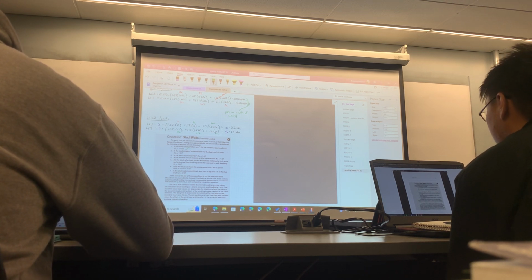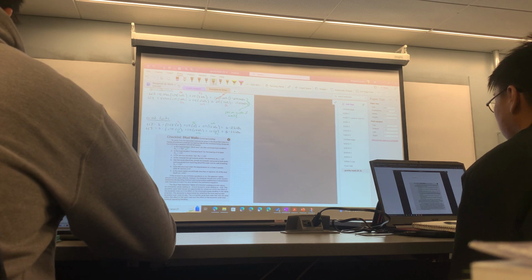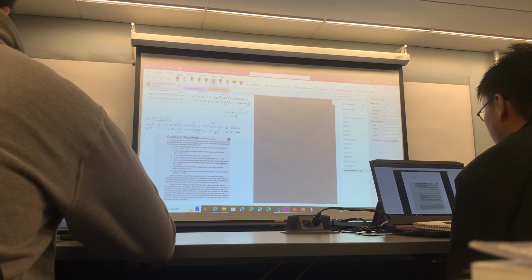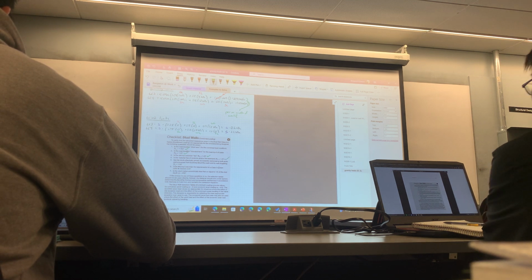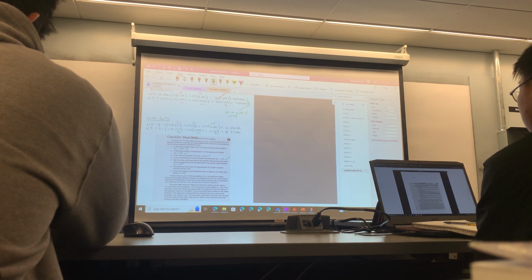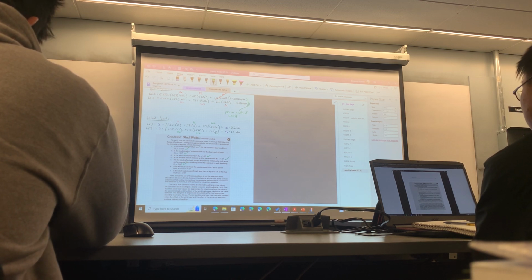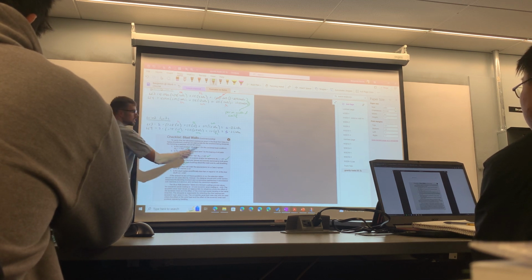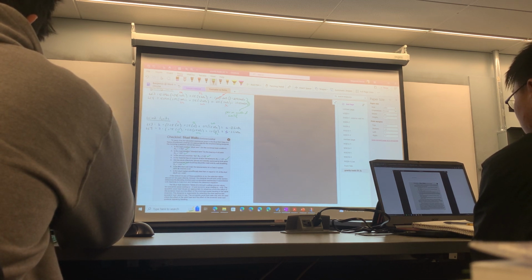Load duration standard term for the bearing of the sill plate, we've got standard term here. Surface condition dry, we can assume it is because it's material free of incisions, KT is 1. Are the studs effectively pinned, laterally restrained at both ends, and prevented from buckling about the weak axis? Because it's in a stud wall system, we can say it is. Effectively pinned and laterally restrained comes down to whether we have sufficient nailing.